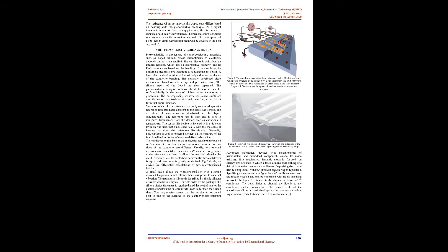6. Parasitic deflection sources. The subsequent deflections are mostly attributed to a mixture of various impacts on the cantilever surfaces. Cantilever deflection can be caused by physical factors such as temperature fluctuations, flow levels, pH, and ionic concentrations. The deflection may also be skewed by secondary effects, including adjustments in surface charge intensity that result in adsorption, ionized material forming as a consequence of the receptor processing operation, or swelling of immobilized receptor materials.